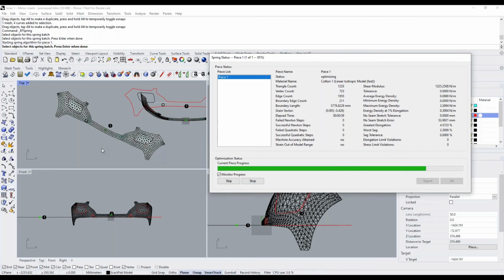And what we've done is we've made a trace tool, as Lucas described, and that trace tool will allow you to trace features. The trace tool is used in a whole variety of contexts. It'll be used, for example, in this situation where you want to trace cutouts. In the marine industry, they trace chine lines on a boat, or markings for marine canvas, or a whole variety of things where you want to translate a point from 3D to 2D and get the exact point or a line or a curve or whatever it might be.